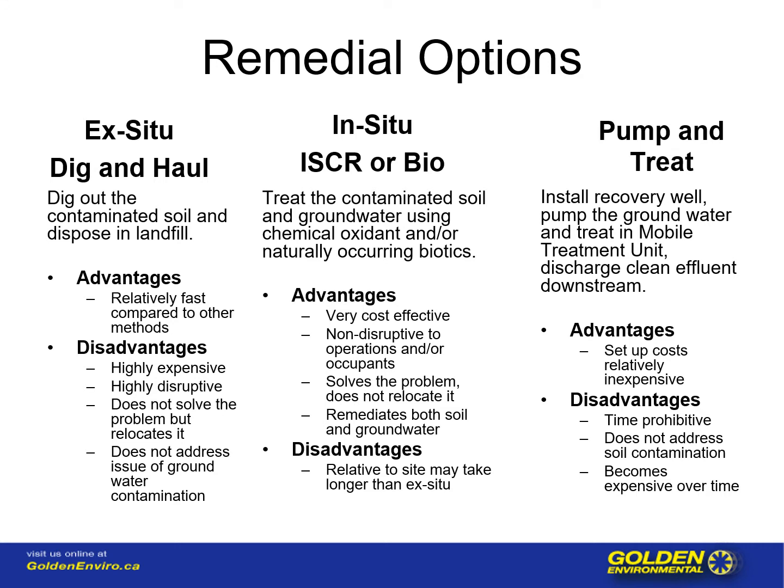This leads us to another process that we have introduced called bio-augmented chemical oxidation. This is where we will begin a remedial process using a chemical oxidant such as sodium persulfate and calcium hydroxide, and then later on during the calcium hydroxide portion of the inoculation add in some microbes to speed up the process. The advantage of adding the microbes is that they continue to work long after we are gone.